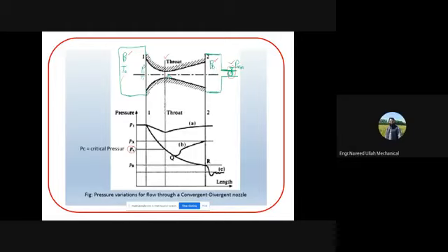And you know very well that the pressure is decreasing to this throat, and the velocity increases. And then it gets its maximum velocity, but it is not the sonic velocity, right, but the fluid is accelerated because this is the convergent section, this is the divergent section.